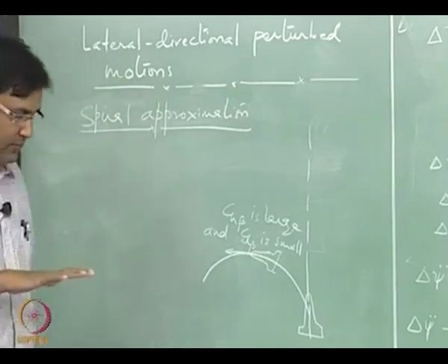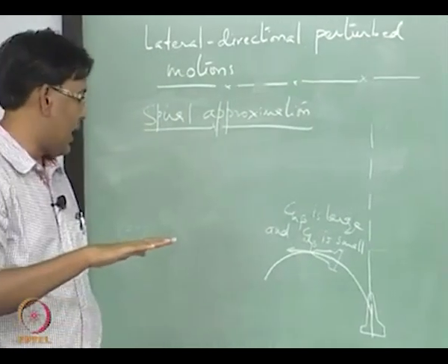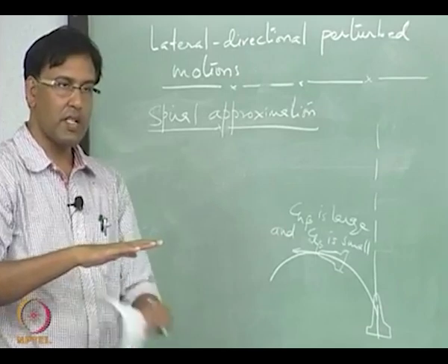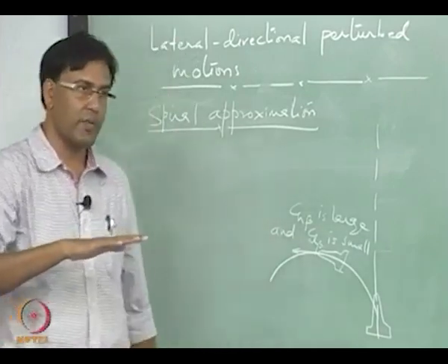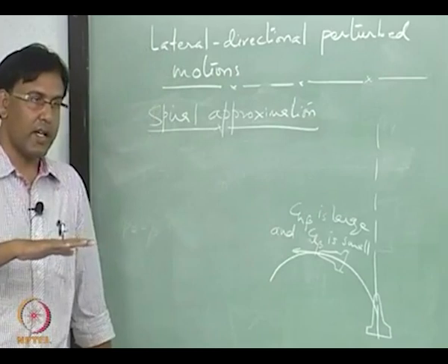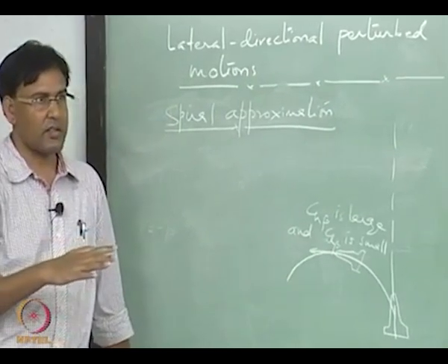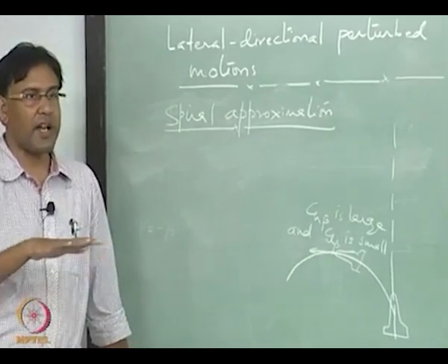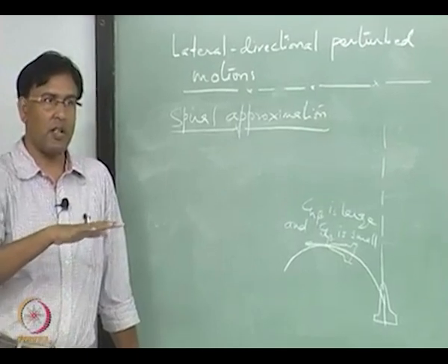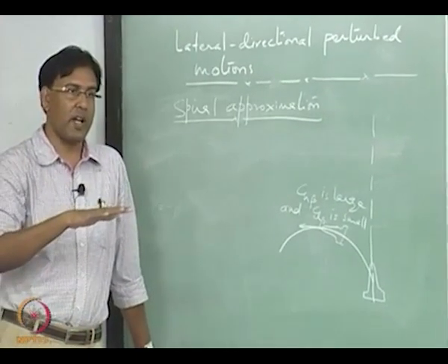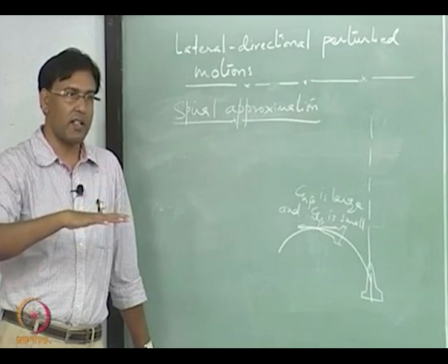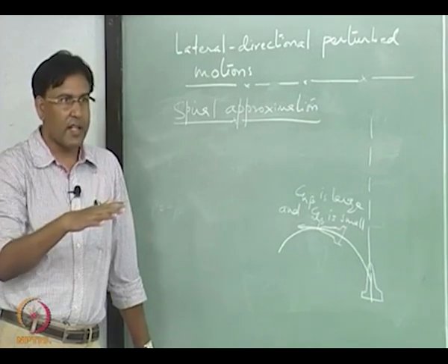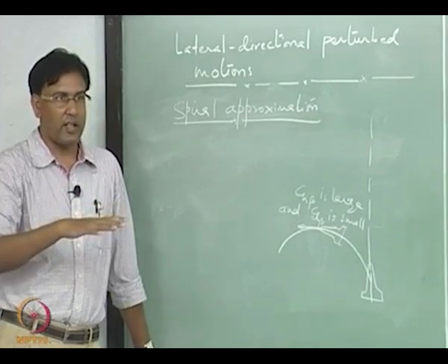So, it is like you are flying like this, and there is a perturbation from the side, a side velocity, a beta is introduced, and then the aircraft starts banking, and this banking is so slow that there is not much change in the roll rate as such, okay. So, it is a steady change in bank angle, and the beta is getting killed.